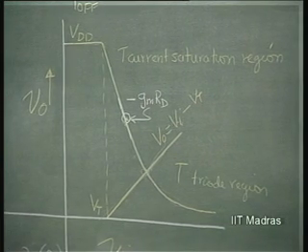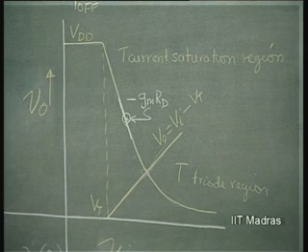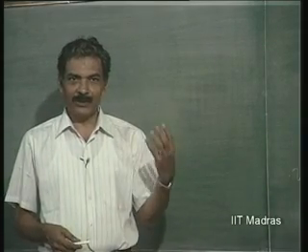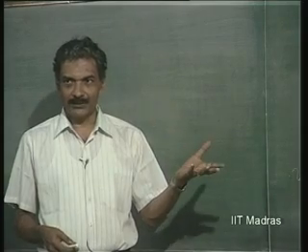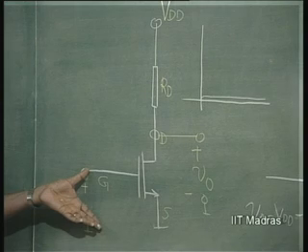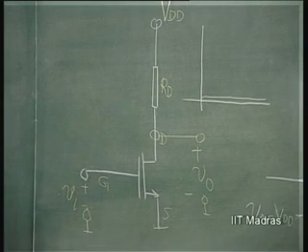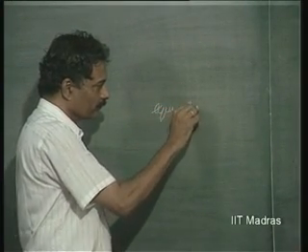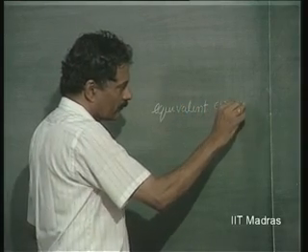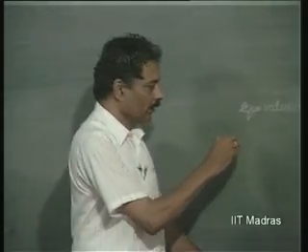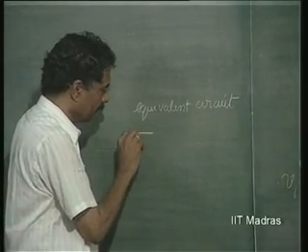Now, therefore, for small signal, and we have also now understood what is meant by small signal. It causes second harmonic distortion, and in order to keep the second harmonic distortion low at a particular percentage compared to the fundamental, we have to use this small signal approximation, and therefore, in the small signal region, the equivalent circuit is what we had included. Equivalent circuit is going to be